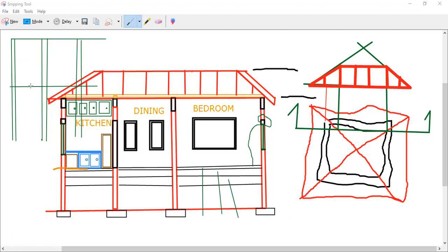The next step would be to offset this down. The first layer from the finished floor is a screed, so you'd offset this down by between 25 to 50. Of course, we still use Through. You then click down and type 100 millimeters, which is the distance for our slab. So we get our slab distance. Click again and move down to get our hardcore, and the hardcore is typically 150.